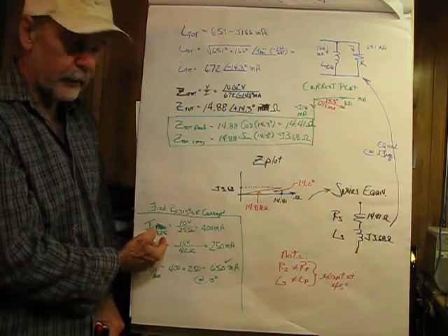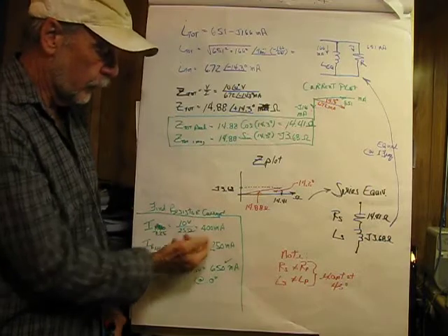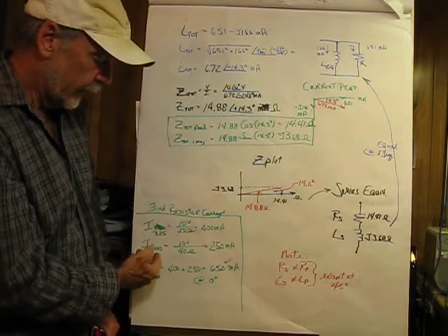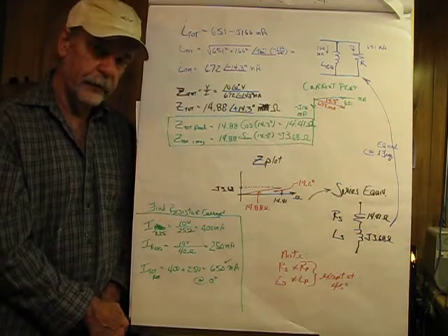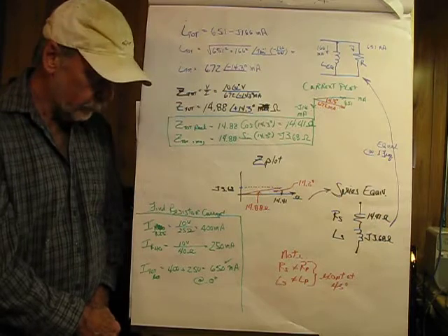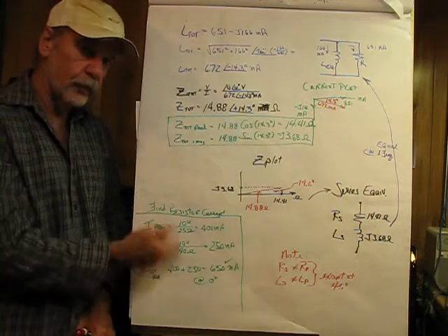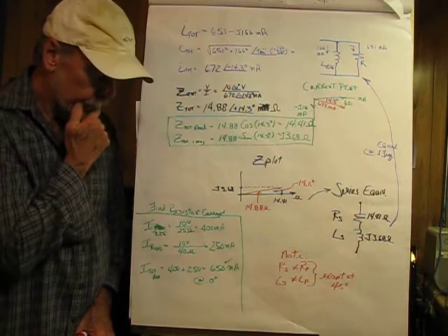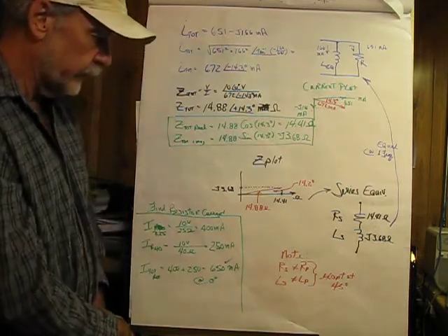Now the last part, if I wanted to find the resistor current, IR25 would simply be equal to 10 volts divided by 25 ohms, giving 400 milliamperes, and IR40 would be 10 volts divided by 40 ohms, giving 250 milliamperes. And, as you might suspect, if we add them together, we should get 650 milliamperes, which we got before, and that checks out. So I'm happy with the calculations.